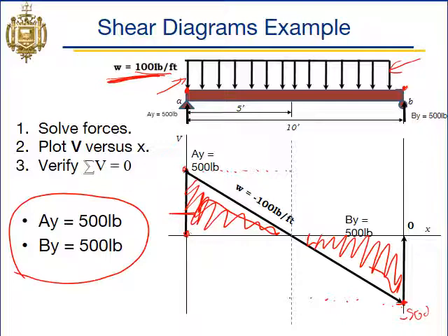With our distributed load, our area under the curve is these small triangles, whereas with that point load we had large rectangles. So the area under the curve of our distributed load is actually smaller. And remember that we can find moment, which is the y-axis times the x-axis. So you can see that our moment is going to be smaller with this distributed load than the point load because the area under the curve is smaller.